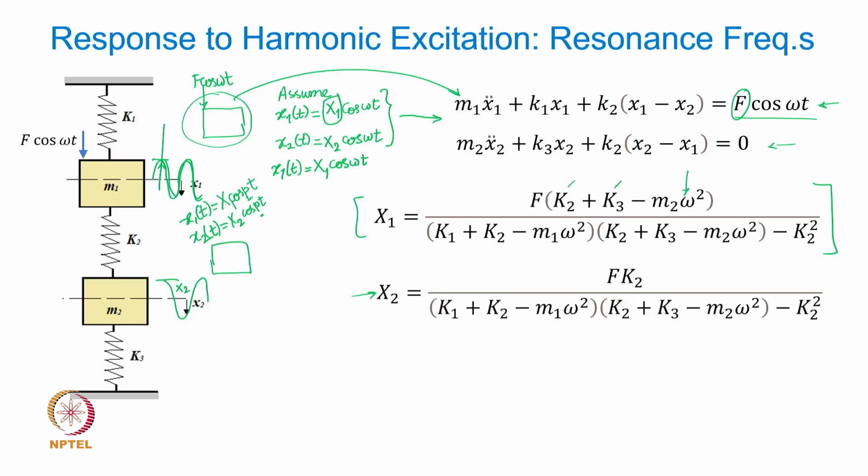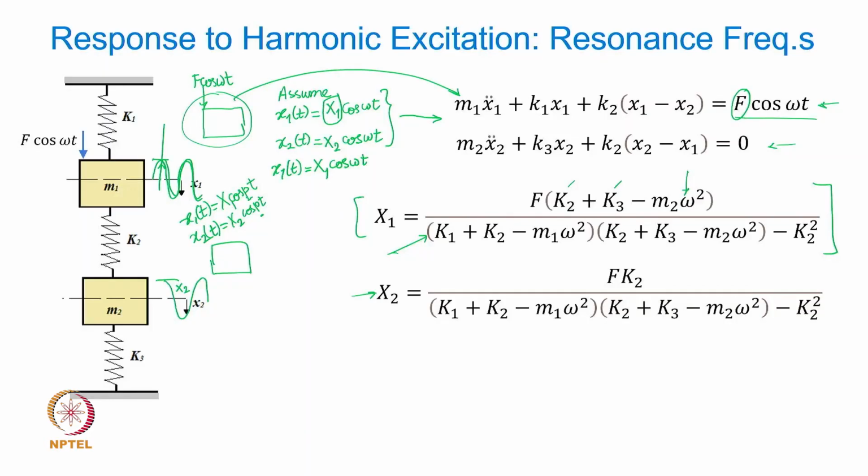When will the compressor vibration become infinite? Very large. Can we say when the denominator is equal to 0? Isn't it? When the denominator, this expression, is 0, amplitude will reach theoretically infinite value. Huge amplitude. And if you notice, these two denominators are just identical.